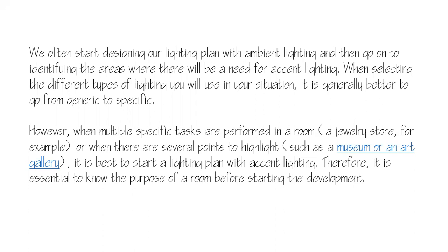That's going to be dependent on the area, the space, and the activities in that area as well. However, when multiple specific tasks are performed in a room, for example a jewelry store, or when there are several points to highlight, such as a museum, as I have discussed earlier, or an art gallery, it is best to start a lighting plan with accent lighting. Therefore, it is essential to know the purpose of a room before starting the development.